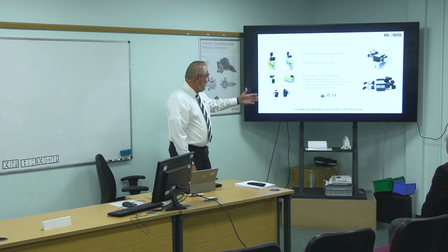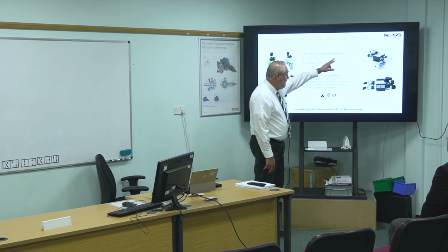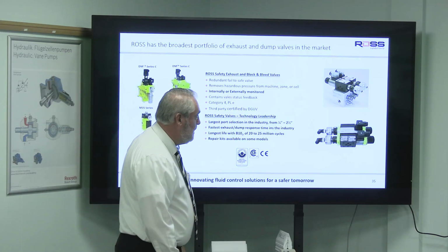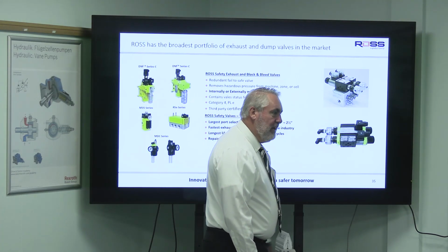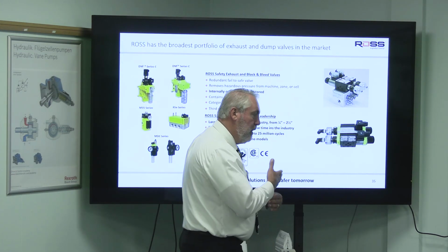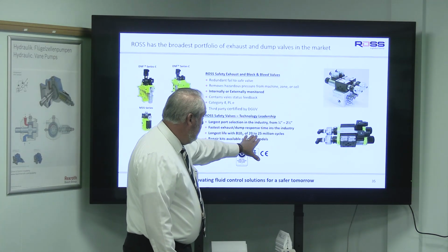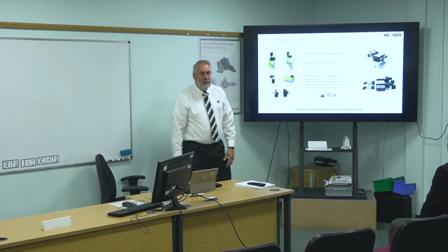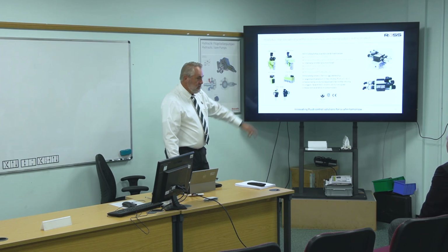And then there are different dump valves. On the pneumatic side, we call it safe exhaust. We call it block and bleed on the other side. Block and bleed valves basically block supply pressure and do the same thing. They redundantly bleed back to tank. We are working on a stackable version that should be out early next year and goes right on the manifold. If we look at the B10D values, it's up to 25 million cycles, so very high reliability. And they have third-party certifications.